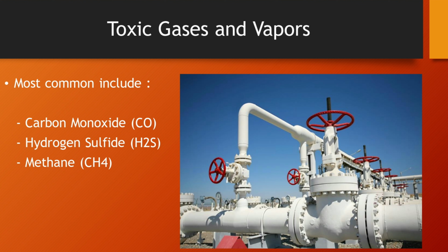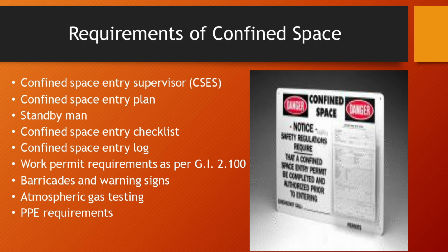Requirements of confined space: Confined Space Entry Supervisor, CSES, Confined Space Entry Plan, Standby Man, Confined Space Entry Checklist, Confined Space Entry Log, work permit requirements as per GI 2.100, barricades and warning signs, atmospheric gas testing, PPE requirements.